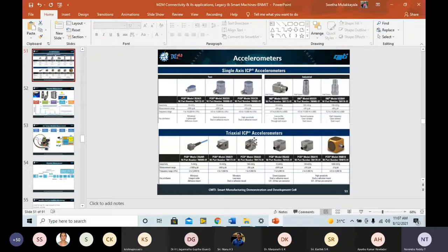On top of it, for any information you want, you add some sensors and take real-time visibility of that particular machine. We don't need complete information from that machine, but if it is only for a maintenance engineer who is very particular about that machine, you take some typical data, a vibration sensor, and do analytics. With the help of AI and ML, you can use RUL, remaining useful life models, and help the maintenance engineer.